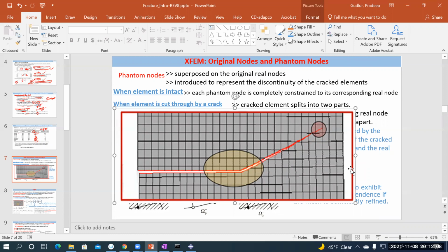It's going diagonally there. There's no edge there. XFEM can do this, whereas the other methods, the contour integral method, debond using VCCT, I should know that. If I have mesh only in that direction, it can go in that direction. Otherwise, the crack won't propagate. So I need to know beforehand which direction the crack is going to propagate.